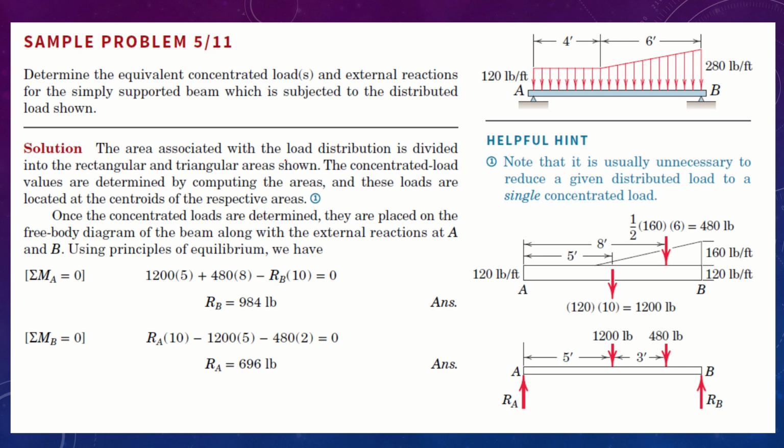Now what you are going to do is very, very simple. You have two uniform loads. You're going to get two reactions. That is, the first resultant load is the resultant load of the rectangle defined by my diagram, this cross rectangle, and the second R will be from the triangle.